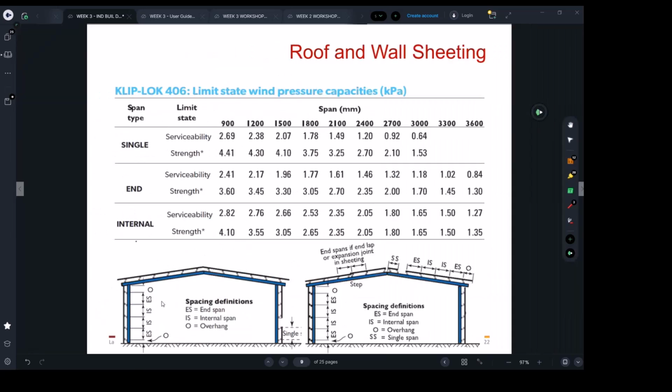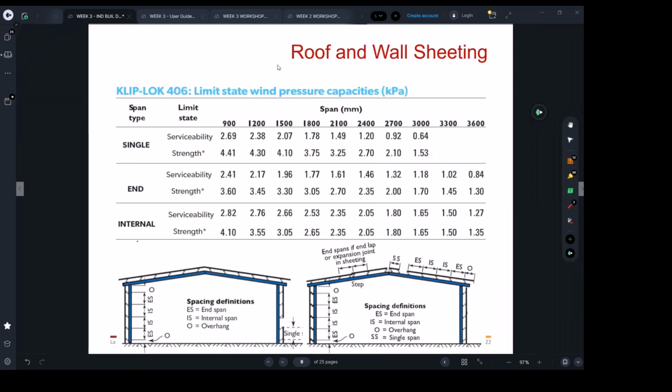Make sure the sheets are spanned to the right floor, because the architects are not engineers. And if the structure engineers did not talk about it, that means they're not responsible. You are the construction engineer. You have to make sure that if you're going to build something, the span will take it, or it can be spanning or acceptable within that span.